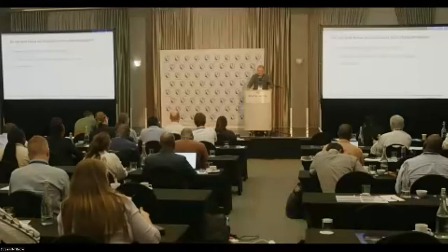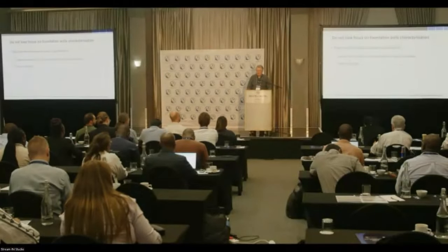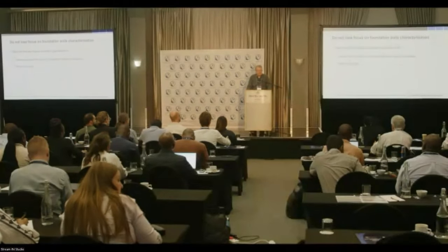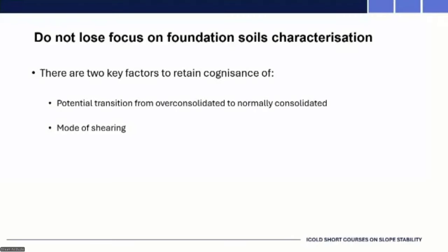To keep it narrower and give a focus that has become evident from some of the investigations, it's obvious, but it's clearly not obvious: this potential transition from over-consolidated to normally consolidated behaviour. That was one of the key things with Mount Polley.